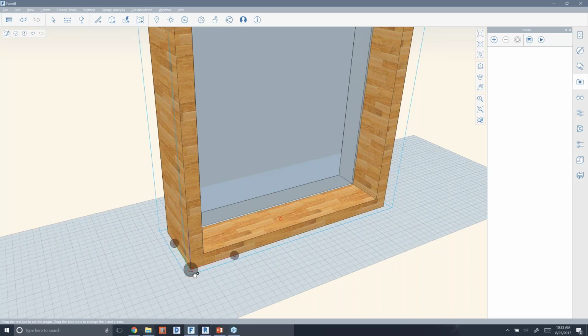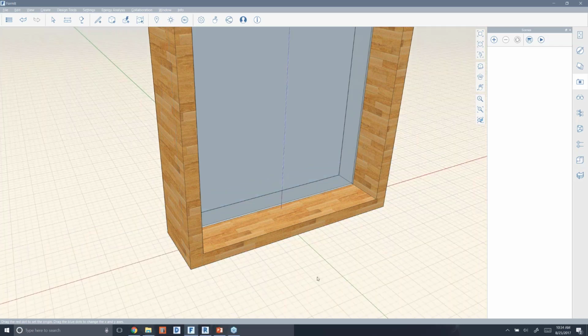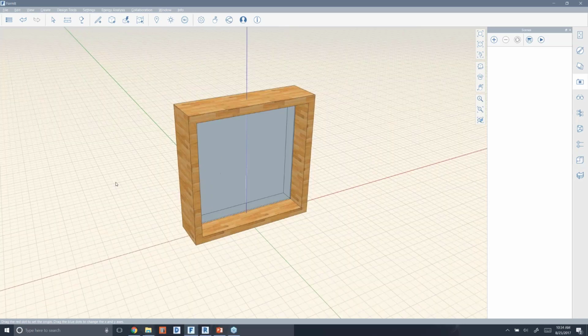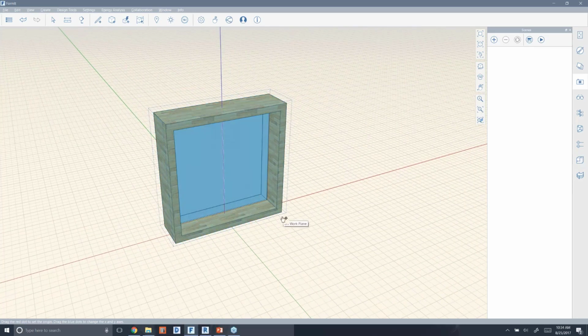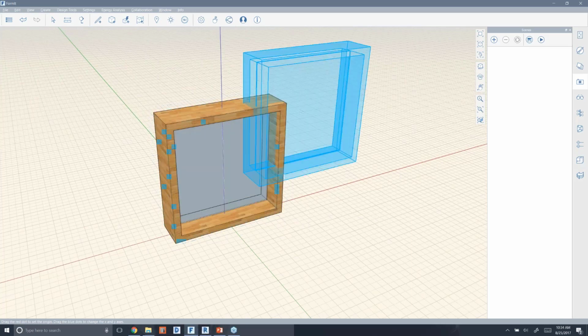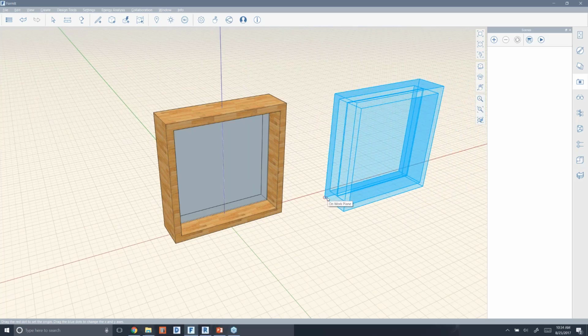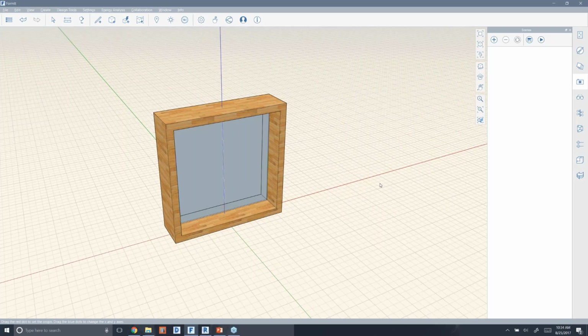So you can kind of choose where you want the placement point to be for the object as far as FormIt is concerned versus where the import location for this object will be when you go into Revit. So when I'm inside the group, I'm setting the placement point for the object in FormIt, and when I'm outside the group, I've got the origin point for Revit import. Hopefully that makes sense, but it's really powerful. You can test that out just by selecting it, doing a Control C and a Control V, and you can see the placement point is already updated to be that back corner. And that's great. When you place from the content library, it will also use that same point. All right, so that's the XYZ origin.